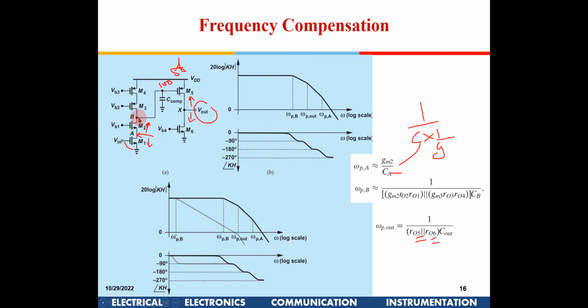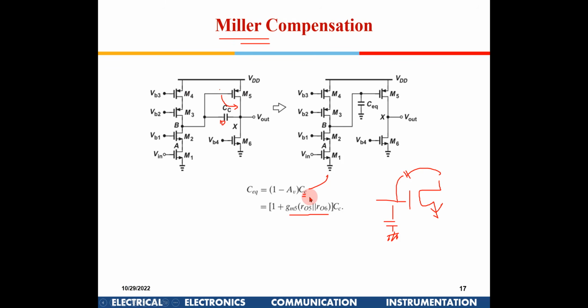The signal moves from here to here, so I have a second node, P out. This node I won't take, because this entire thing is an effective resistance for me. Then I have this node here, and when the signal comes to here, I have one more node. So I have to see my signal path, and wherever there is an RC combination, I have to look after that. Okay, clear.